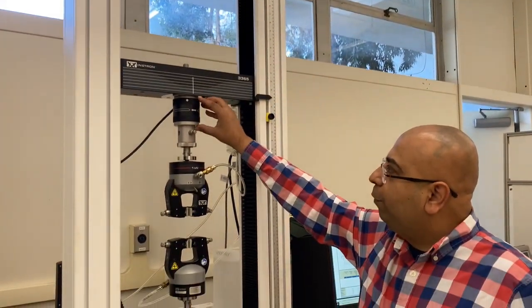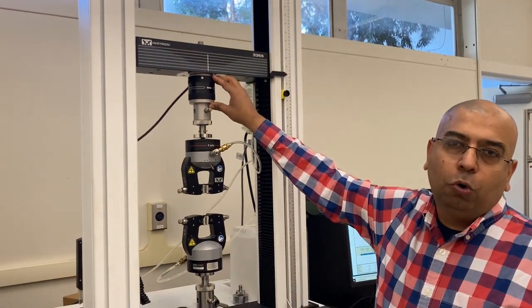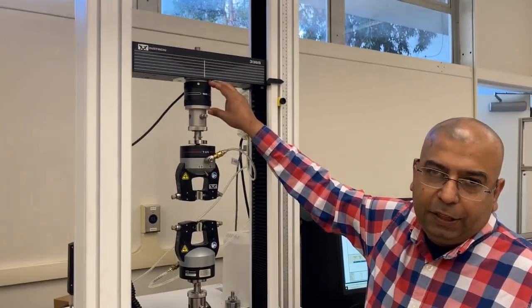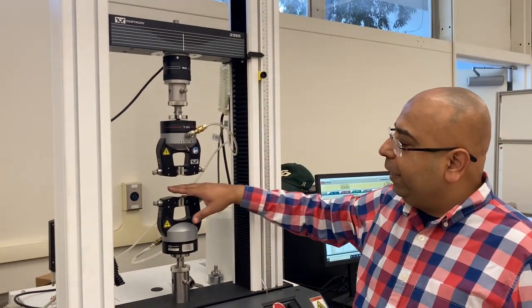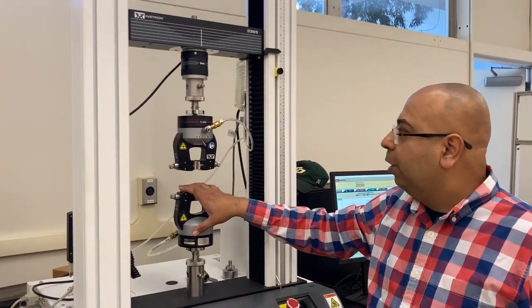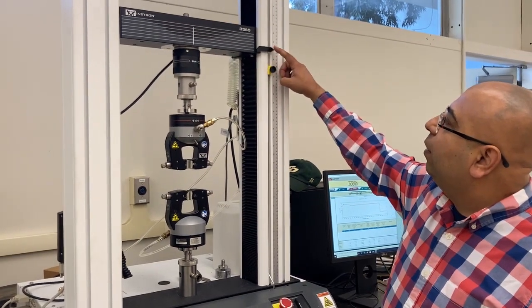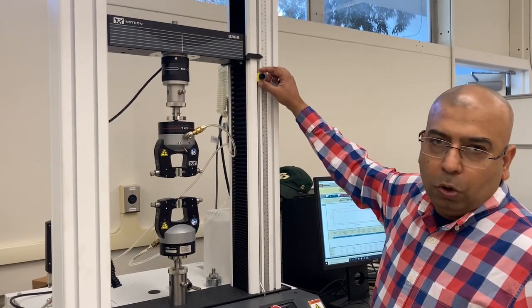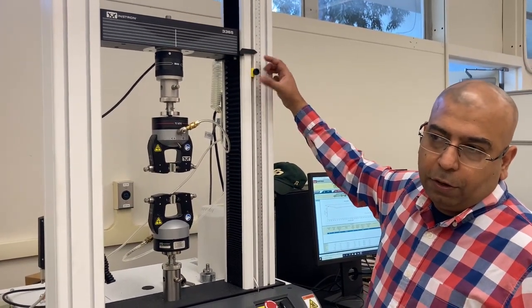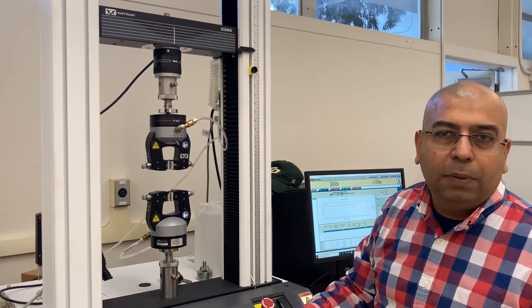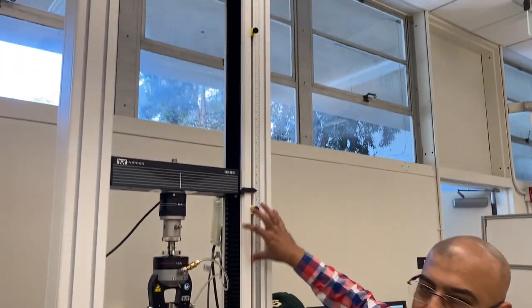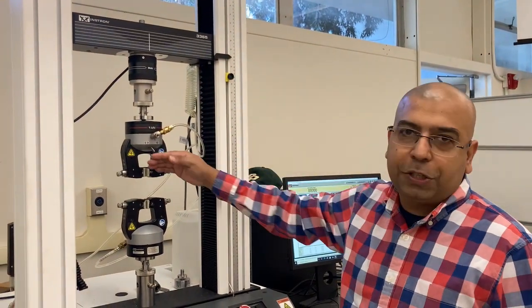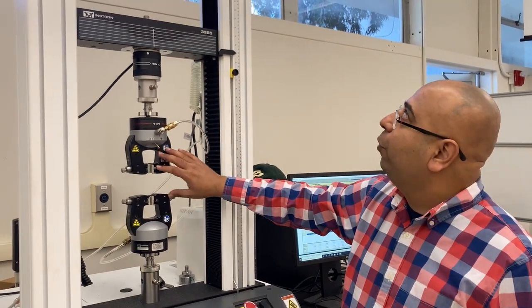Now what we have right here is what we call as load cell. So that is going to get damaged if we hit the parts of the machine into each other. So we have a protection right here. When this arrow metal piece going to hit this yellow point or yellow trip button right here, it's going to stop the machine. It's not going to let it bump, but it can be moved up and down. So it could happen that somebody has set it really low, it still bumps into each other. So we have to take care of that.